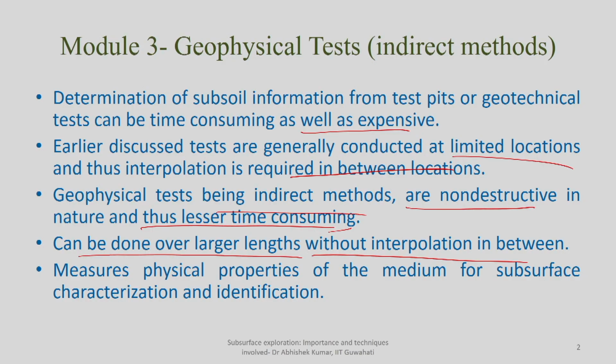What it does, depending upon the physical properties of the medium, depending upon which kind of geophysical test you are using, each geophysical test will be able to determine some variation in the physical properties of the medium, either using those physical variations directly, or by using some empirical correlation, you will be able to determine what kind of soil deposits are there, what are the strength characteristics of the soil deposits, which thereafter you can use for subsurface exploration, for interpretation, for foundation design, even for dewatering purpose also, and so on and so forth.